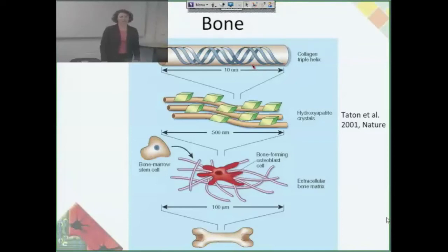So I talked a little bit earlier about how bone is a natural ceramic, and I guess what we're talking about here is that we're trying to mimic bone in order to replace bone, right? So it's helpful to look at the ultrastructure of bone. What you have is mineralized proteins, basically, and so while ceramics that we might make in the lab are really brittle, bone is not that brittle because it's held together by a collagen network that's really strong in tension, and that can also swell with water, and so all of this leads to a decrease in the brittleness. So if we could figure out how to mineralize collagen matrices like bone is, then we could make a better bone, but we haven't yet.